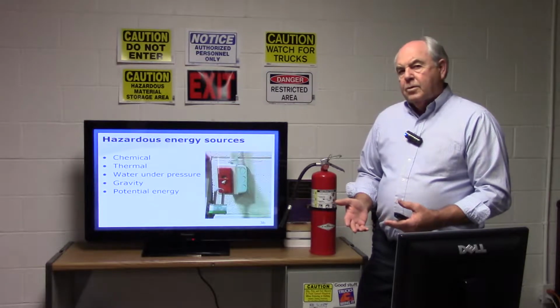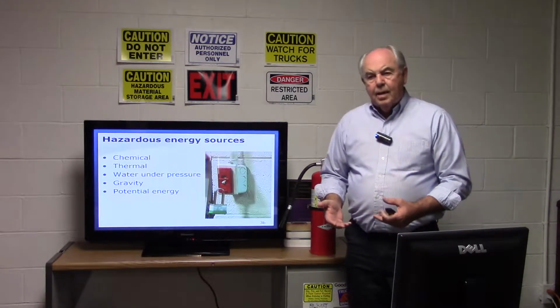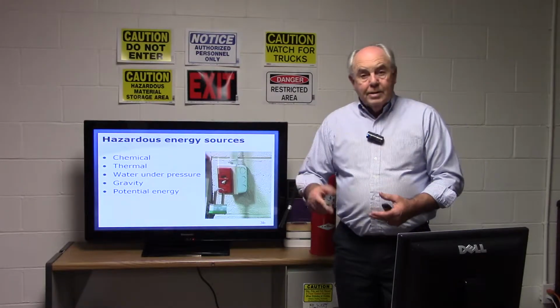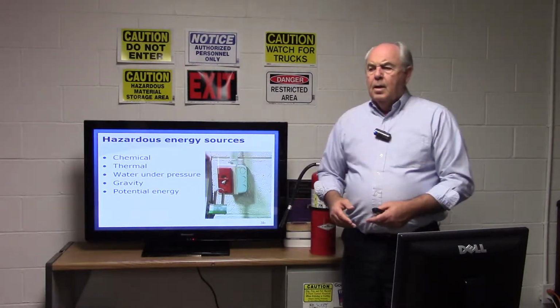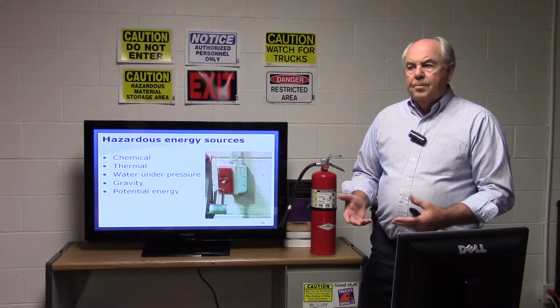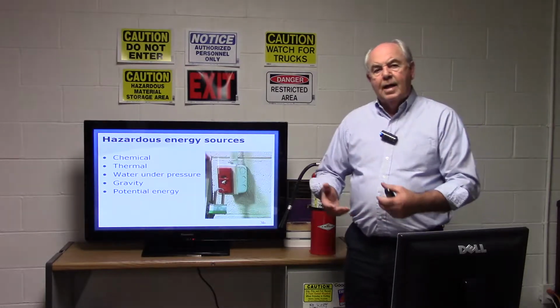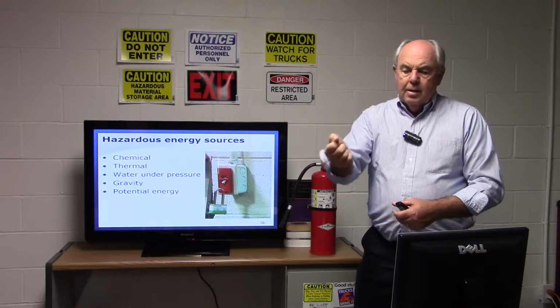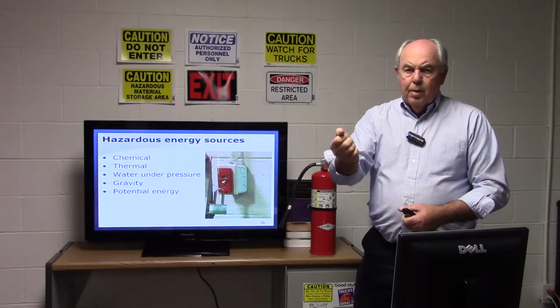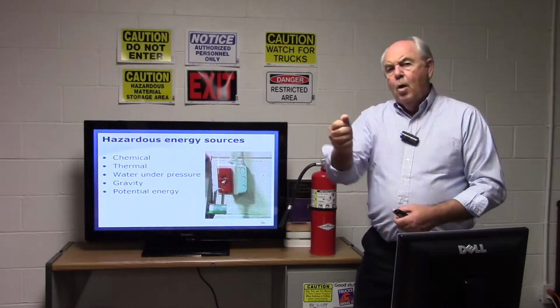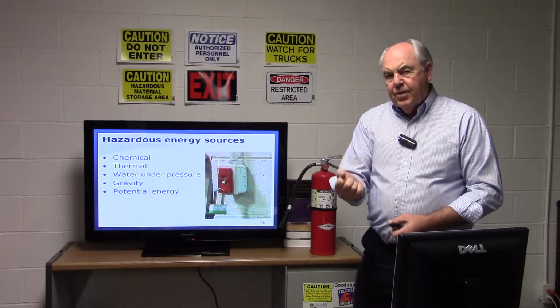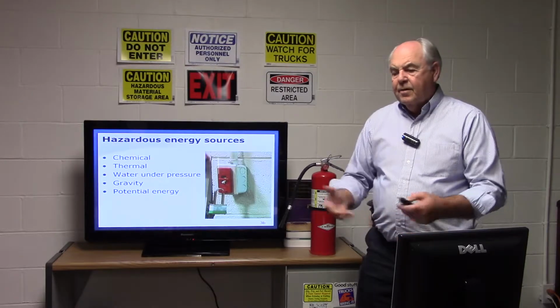Same way with a hydraulic line. I know today a lot of times when you turn off the power to a hydraulic pump, they'll depressurize automatically. But some of the older ones do not. If you don't de-energize that hydraulic line or lift the pressure off from it, when you start taking that wrench and you're taking the bolt loose that holds that line on, what's going to happen when you get down to that last thread? Now, it could be all in your face.